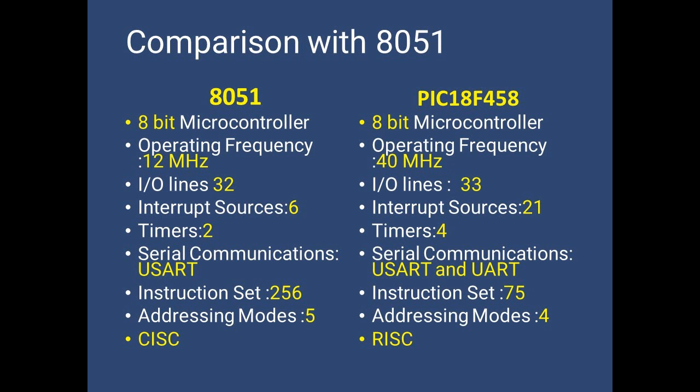In the case of 8051, we have a USART, which means Universal Synchronous Asynchronous Receiver and Transmitter. In the 18F series, we have a USART, but along with it we have a different unit used for synchronous kind of communication, and a whole lot of serial communication buses are available.